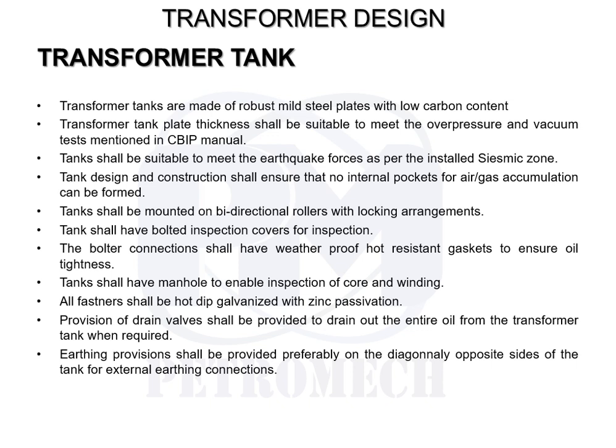Tanks shall have bolted inspection covers for inspection. The bolted connections shall have weatherproof, heat resistant gaskets to ensure oil tightness. Tanks shall also have a manhole for visual inspection of the core and winding assembly from outside.